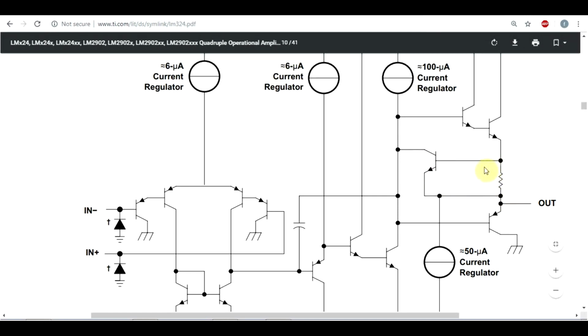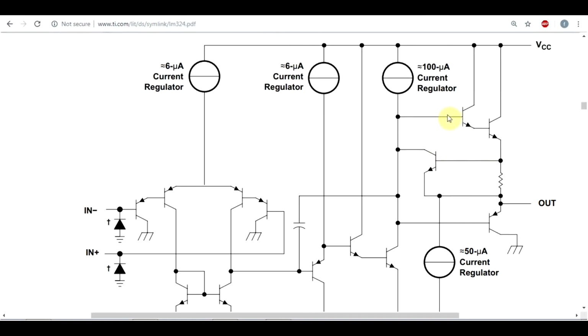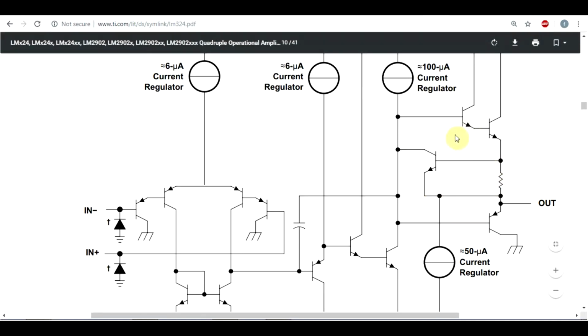So we've got this resistor in series with the high side output, and when the voltage drop on this is high enough, it will drive this transistor. So again, apart from the 0.7 plus 0.7, 1.4 volts drop on these two transistors, we will have an extra 0.7 volt drop on this transistor at the point at which the overcurrent limit kicks in. So depending on how the output stage is built, you will have various voltage drops which are current dependent.